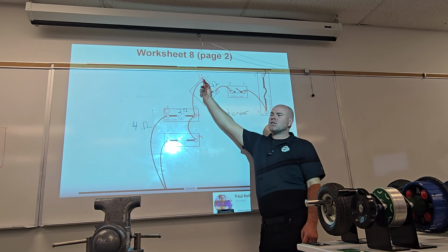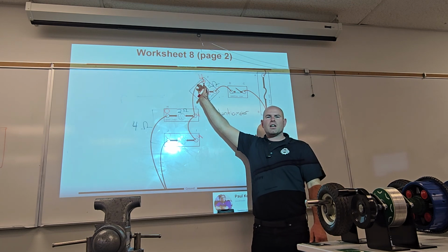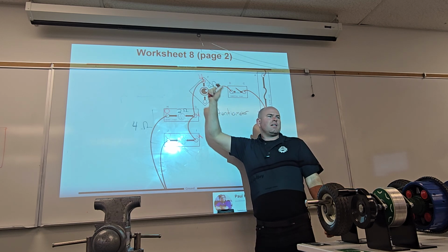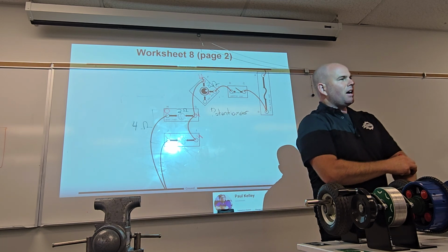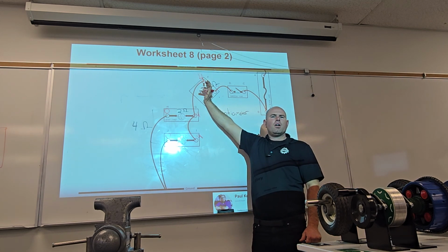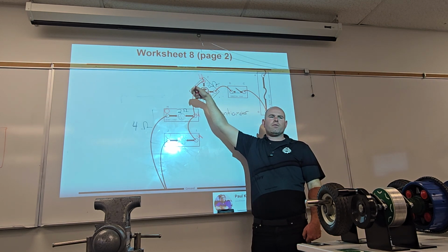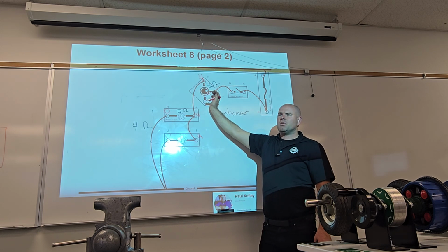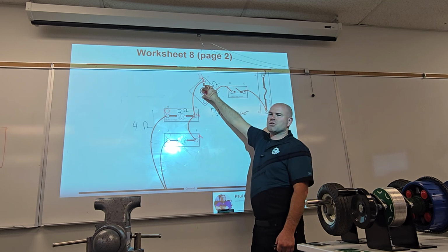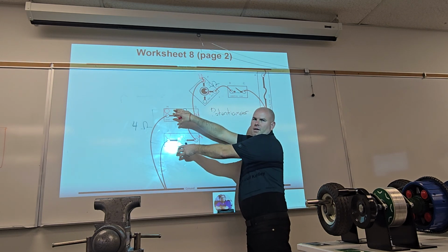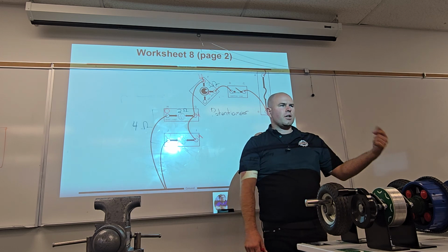This is consuming 8 volts, but you know what it does? Basically nothing. We put a resistor in. Let me just explain though. This dimmer, all it does is take the voltage it consumes and make it into heat. So it kind of sucks because this is taking electrical voltage and making it into heat, and these are just glowing dim. But remember, when you're on that long trip, that's what you asked for.